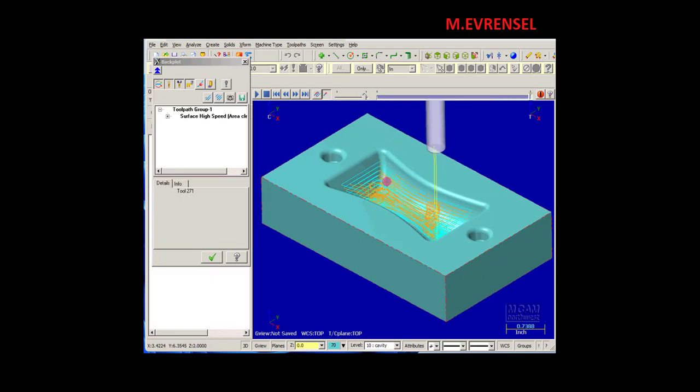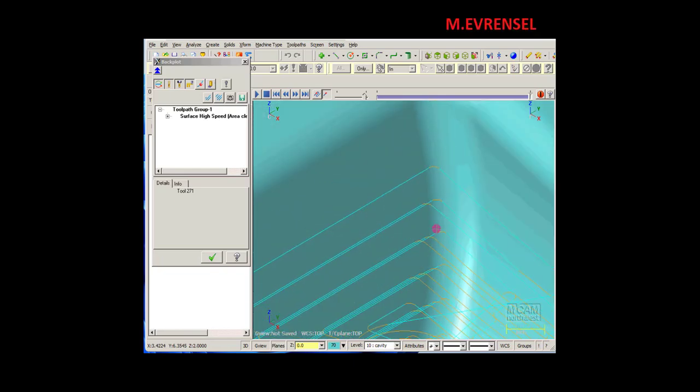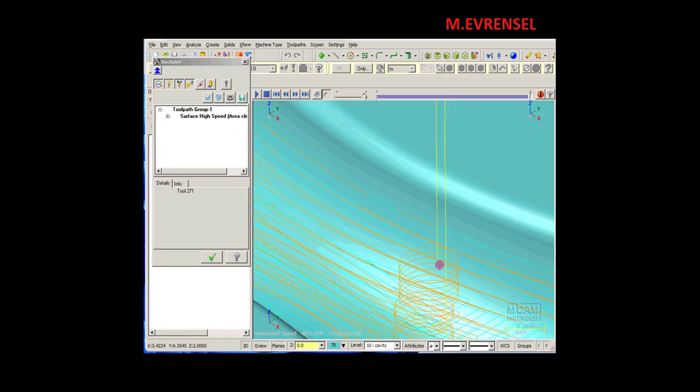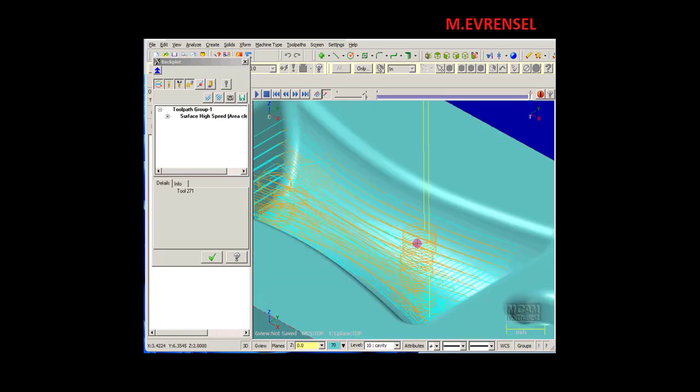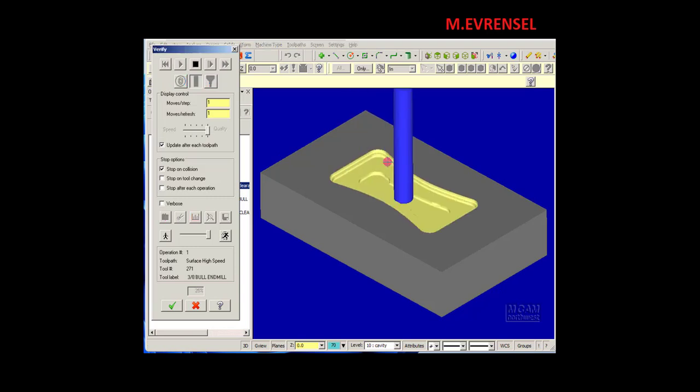and zoom in a bit here and study the toolpath, I have my arc motions in my backplot turned to orange and linear moves are blue. So you can see nice arc motions in the corner here, and also the full helix is an arc. Now we can go ahead and verify this. And we're taking 16th inch step downs all the way through.